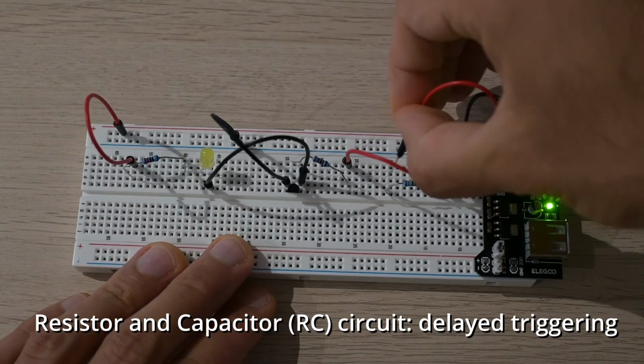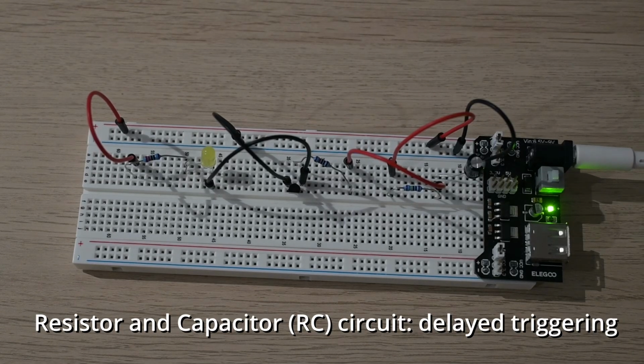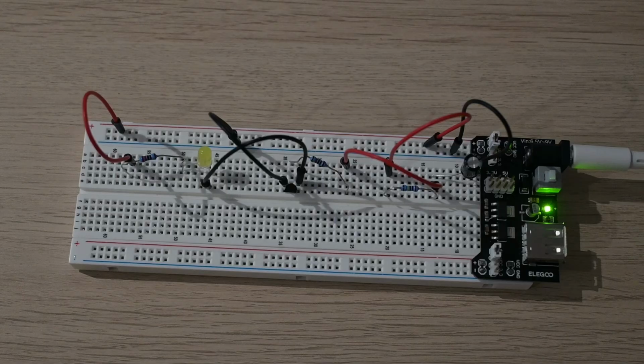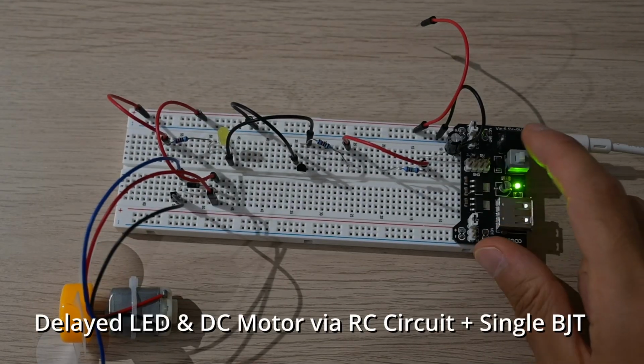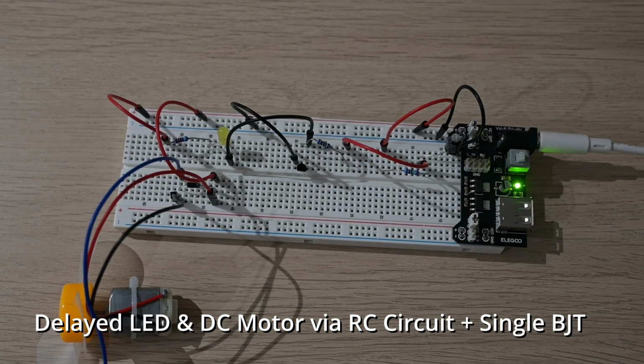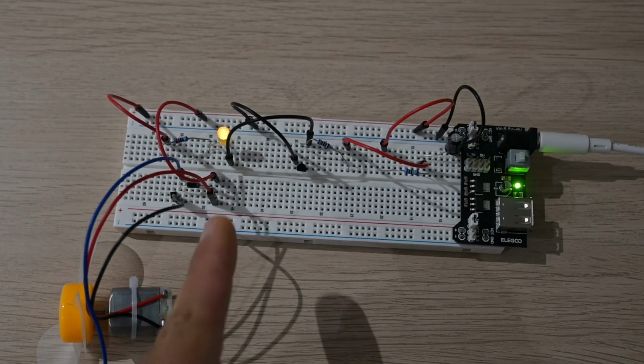When setting up a resistor and capacitor circuit, or RC circuit, we can take advantage of its predictable charging curve to delay the activation of a transistor, which in turn can activate another set of components. Depending if the transistor is a bipolar junction transistor, BJT, which is current controlled, or a MOSFET, which is voltage controlled, they would have different current or voltage thresholds at which they allow current to flow between the collector and emitter, in the case of a BJT, or drain and source for a MOSFET.